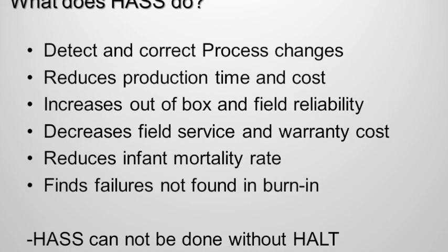So this will decrease field service and warranty costs. It'll reduce the infant mortality rate, and it will help you find issues you would not have found in burn-in. So all of this will reduce that infant mortality period. And there's no way to develop a HAS profile if you haven't first done HALT testing because it is established in what's learned in HALT.